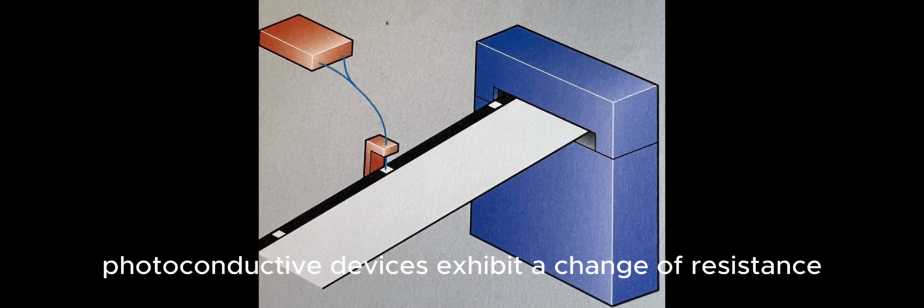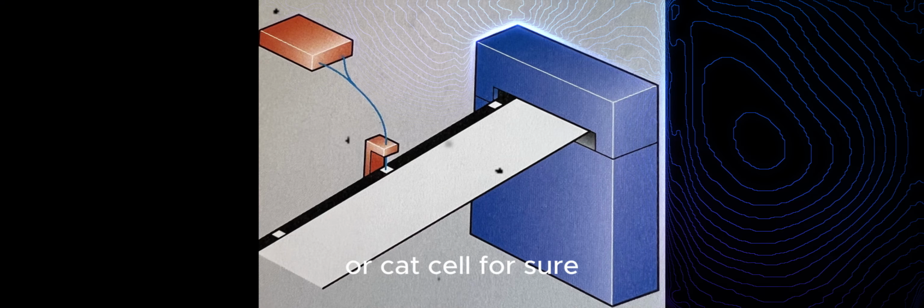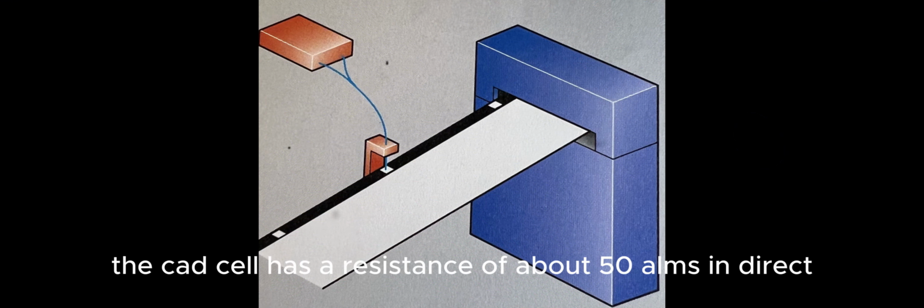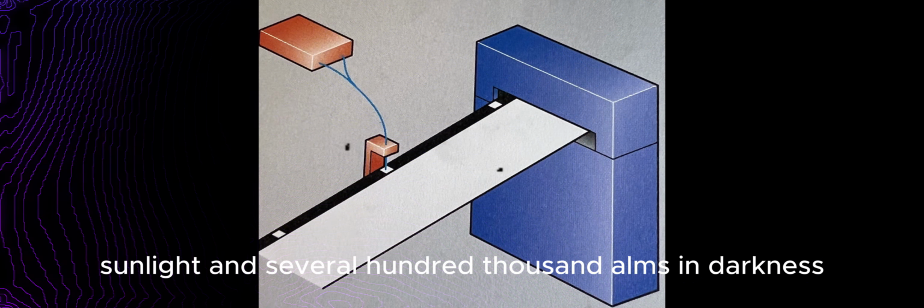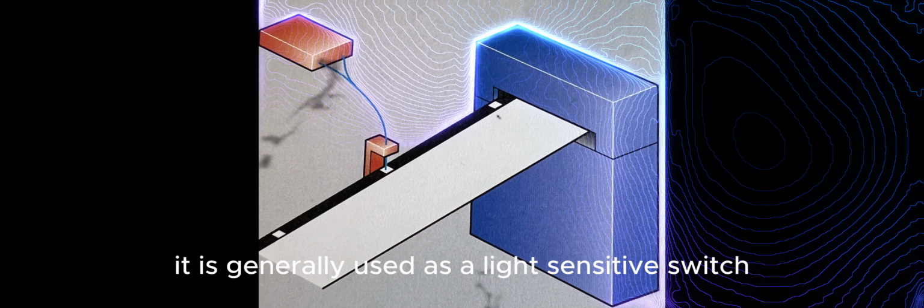Photoconductive devices. Photoconductive devices exhibit a change of resistance due to the presence or absence of light. The most common photoconductive device is the cadmium sulfide cell, or CdS cell for short. The CdS cell has a resistance of about 50 ohms in direct sunlight and several 100,000 ohms in darkness. It is generally used as a light-sensitive switch.